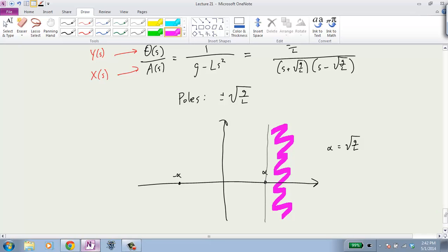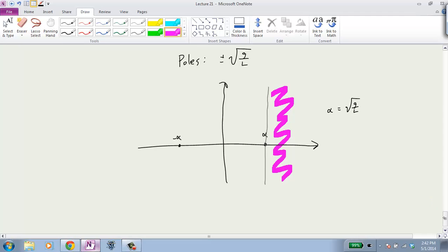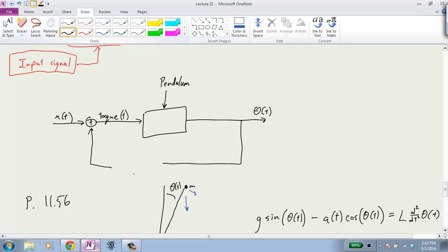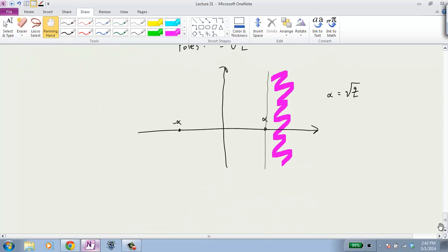So what we're going to do first is say, what if we put proportional feedback? What if I make this thing minus k? I'm going to put a subscript 2 just because of the way the variables are labeled in Simulink. So minus a constant times whatever the angle is. If you think about what this feedback will try to do, it will try to put a torque in the opposite direction of the angle so that it'll bring it back up, right? Now, we can mathematically see what that would do to this system.